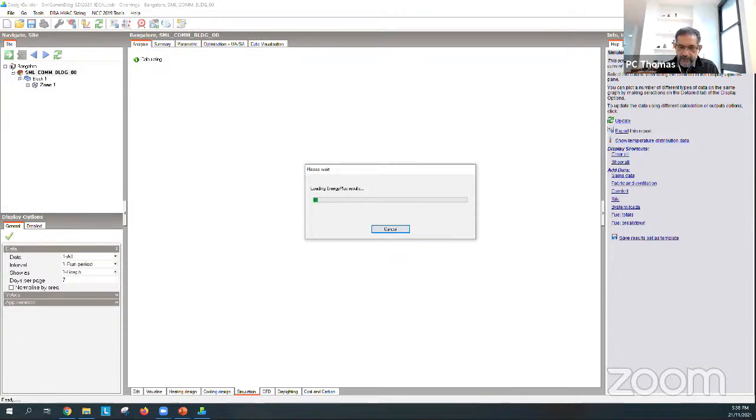When you do air conditioning, it assumes the building is air conditioned. When you do natural ventilation and you switch off air conditioning, then you're doing only natural ventilation. You need to turn both on, and to do that, you need to use what's called the mixed mode operation of the building. Okay, so you need to set your control strategy very carefully.